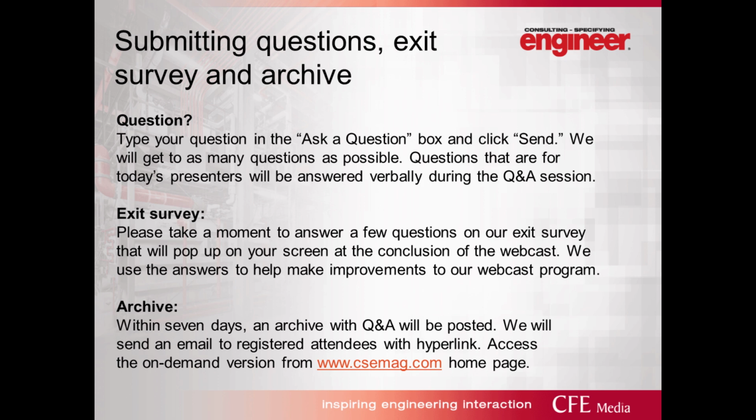Sure. Thanks, Amara. As mentioned, the starting versus running wattage are different. And so the best way to minimize the size of your generator is to place various loads into steps.